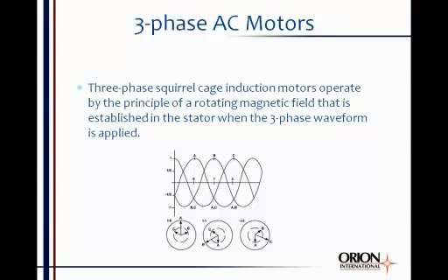views below the waveform. At time t equals 0, the net waveform is vertical at 0 degrees. And then you notice at time t equals 1, which is when B is peaking, it is rotated 120 degrees to the left, counterclockwise.